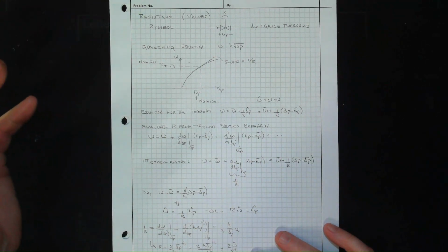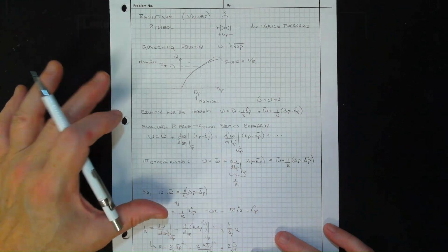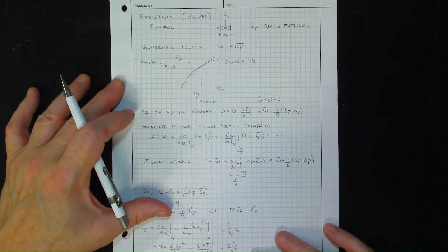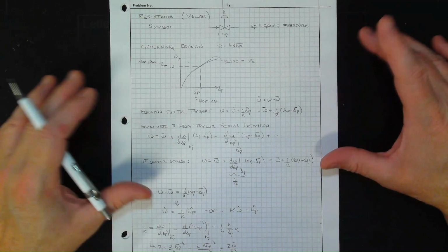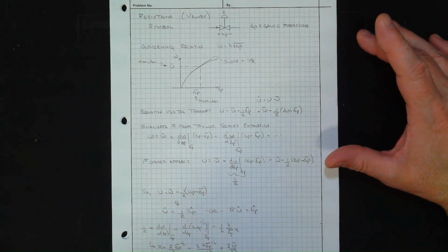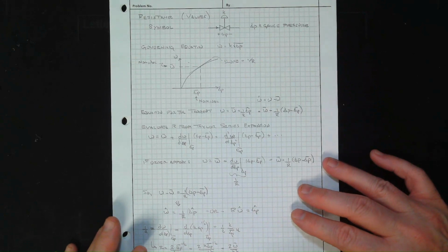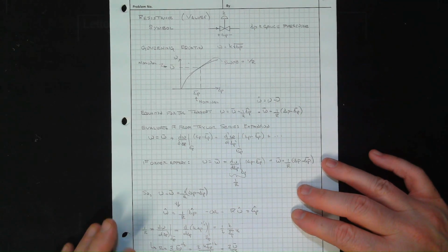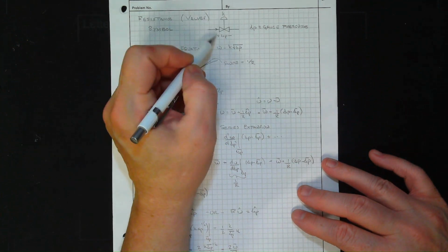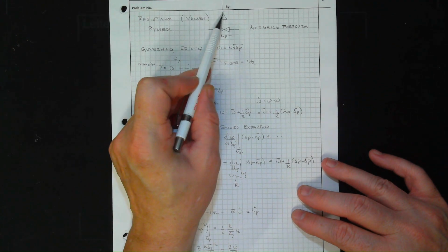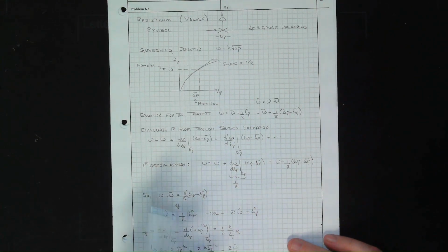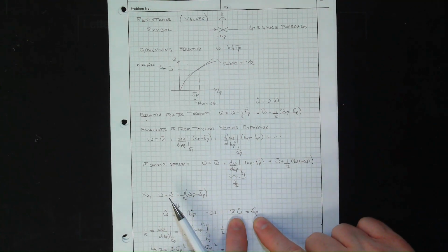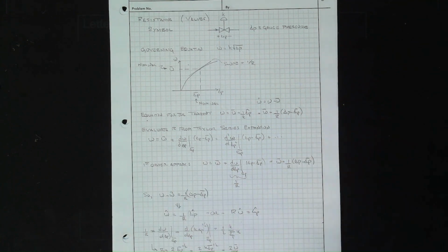If you go on to more sophisticated courses in systems, you will spend much more time dealing with nonlinearity. We're more focused in this course on exposing you to them and letting you see the process. As you move on, this is something you may need to get into with more depth. So this is how we handle valves. They look like this. Knowing omega and knowing K, boom, you have R. The linear model is just what you would expect based on resistors, and these are an analogy.